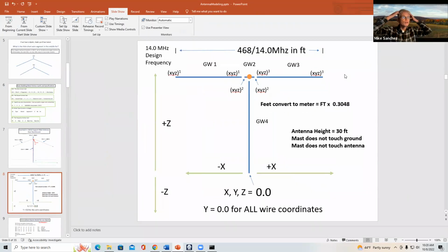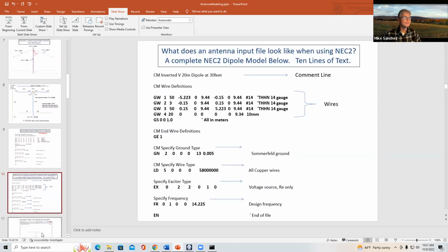We're going to do it for 20 megahertz, the bottom of the CW band, or the data band, which will give us an antenna that's a little too long on purpose, because I want to show some things about that, and we're going to manually trim it. Start out by calculating the total length. This is going to end up being feet. Convert that to meters.